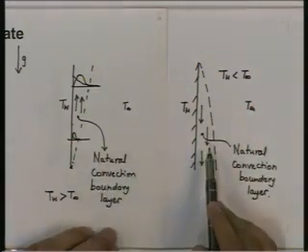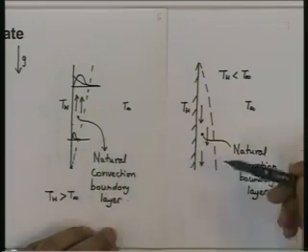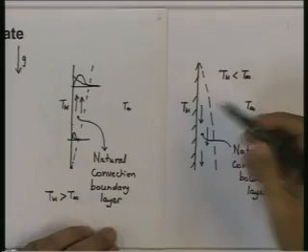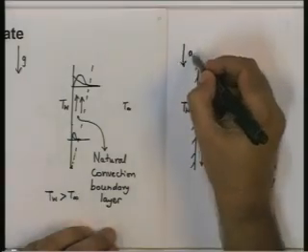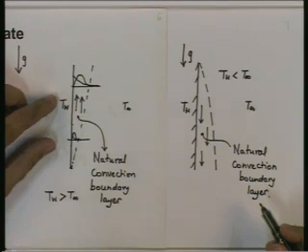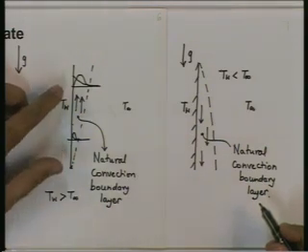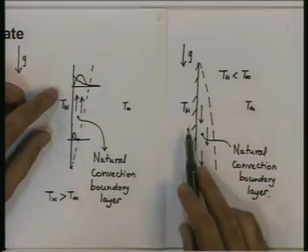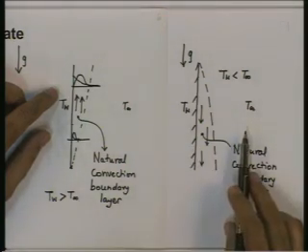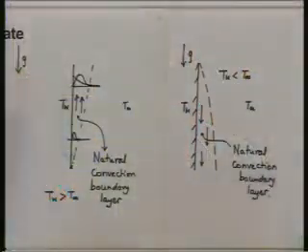These situations are more or less symmetric to each other in the vertical direction. If you assume that gravity is acting downwards, the situation of a hot wall facing a fluid is similar to the situation of a cold wall facing a fluid with the vertical direction reversed. Here fluid tends to move up, here the fluid tends to move down. After having looked at the basic process for a vertical flat plate, we look at a correlation, the recommended correlation for a vertical flat plate.